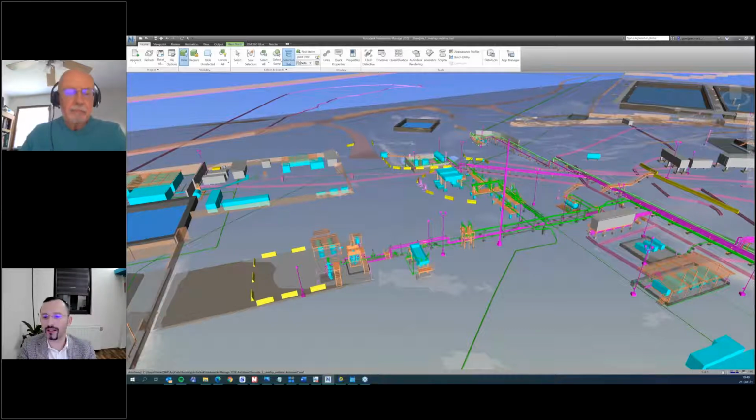Yes. The biggest challenge is to run and to process the point cloud. If you are using point cloud directly into an engineering platform, you need to have for each user a very powerful workstation, which is also very costly. On the other side, we use just one powerful workstation to process point cloud. We then process point cloud in EdgeWise, and when EdgeWise processes the point cloud, we use directly the file from EdgeWise, which was very easy.